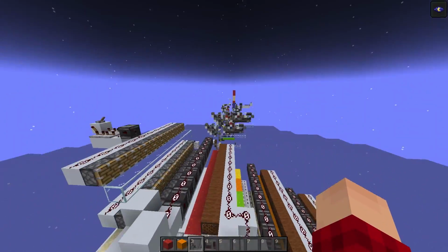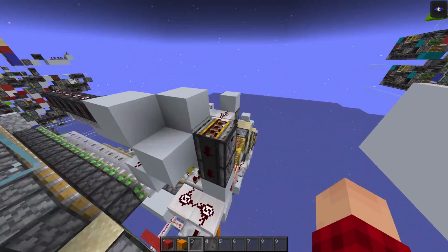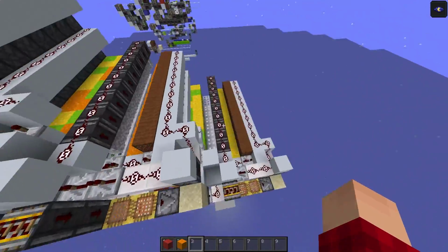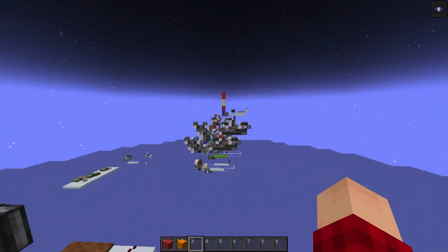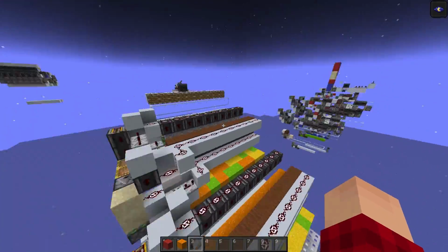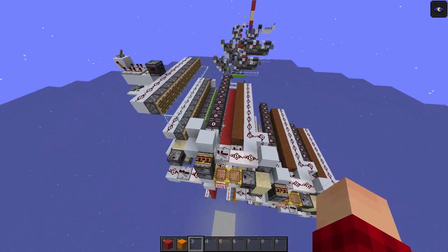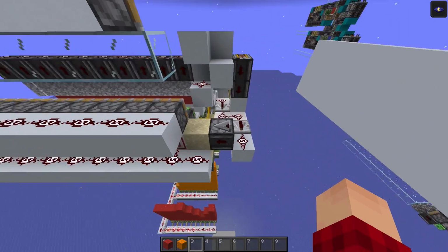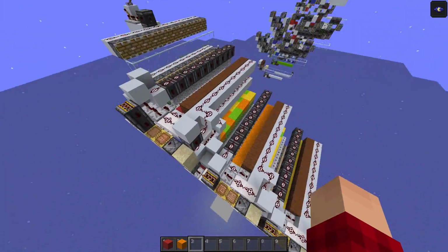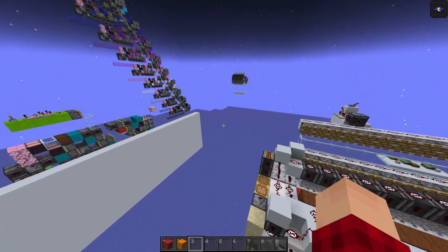And the other disadvantage, of course, is that this technically isn't one wide tileable, or I should say it's not infinitely tileable, because we need these control circuits over here. And so if you want to do this for a long row of blocks, you could possibly stagger it back and forth. But overall, this kind of is just more complicated and harder to work with than our infinitely tileable versions. So let's get on to that.